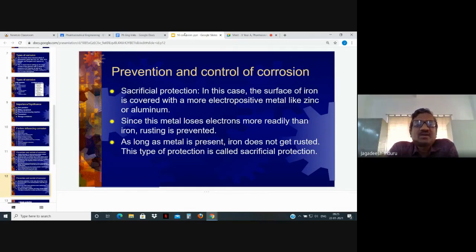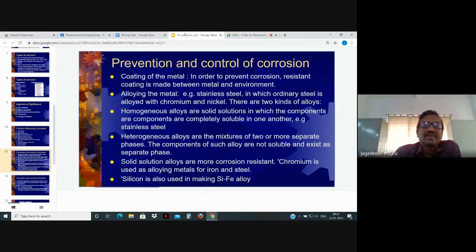So one methodology approach that we have previously seen is alloying of material and coating of material. Obviously, the design of the equipment is also going to help us, because a design with any crevices or enclosures, or stagnancy of our reaction mixture or corrosive mixture, is going to have a damaging effect on the equipment. That is the reason we take these factors into account.